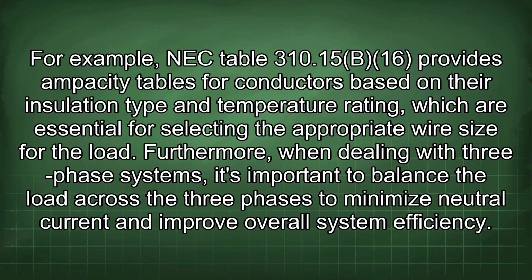For example, NEC Table 310.15(B)(16) provides ampacity tables for conductors based on their insulation type and temperature rating, which are essential for selecting the appropriate wire size for the load.